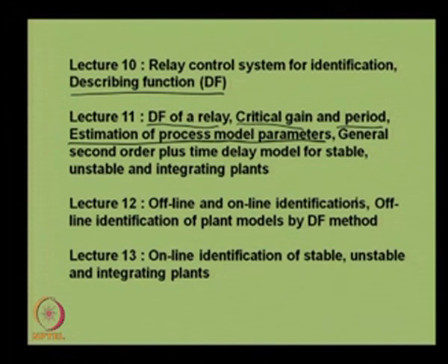Process dynamics can be assumed in the form of a first order plus delay transfer function, given as k e to the power minus theta s upon T1 s plus 1, where theta represents the time delay of the process model, k is the steady state gain, and T1 is the time constant of the first order process model.